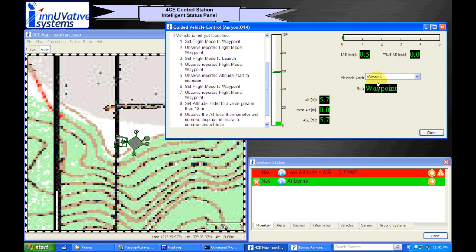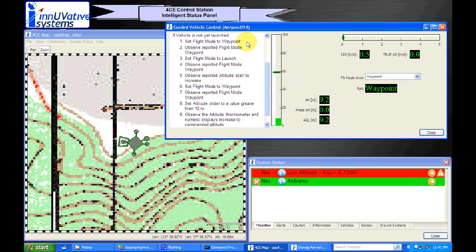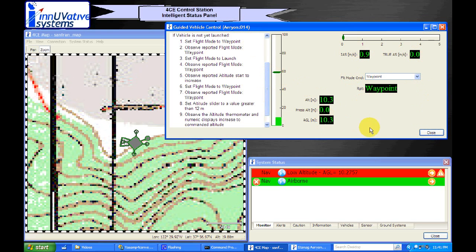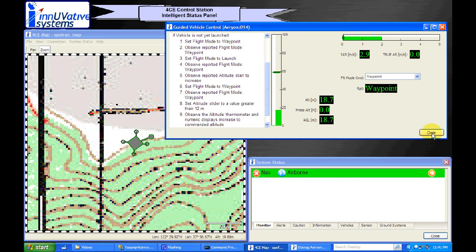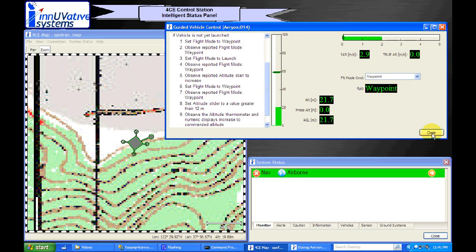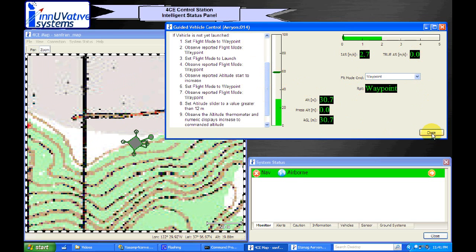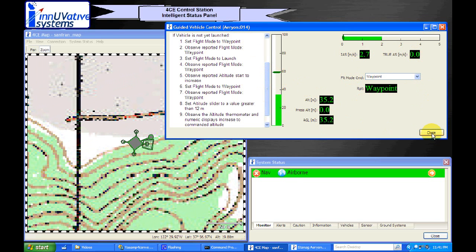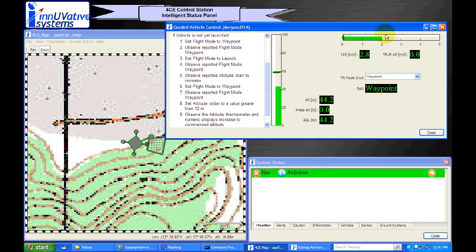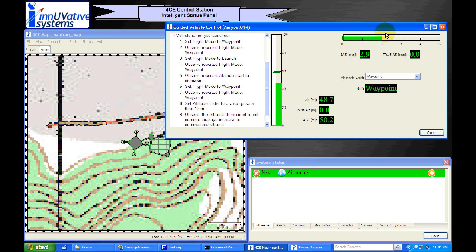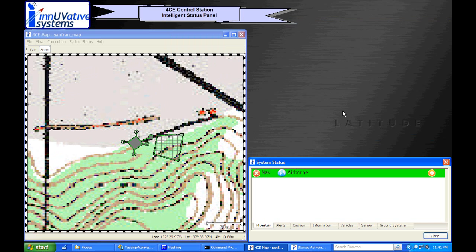If, however, there were some more corrective action that needed to be taken on a next dialog, instead of a close button, this would be a next, and it would open the next dialog required along with the text that is associated with that dialog. And in this way, the operator has an immediate ability to be self-guided through the corrective action. Where it's possible to automate the corrective action, that is of course a faster way of implementing it. However, in many cases, the operator is still desired to be in the loop. Therefore, this way makes it not quite automated, but still very quick, very effective, and easily executed even under stress.